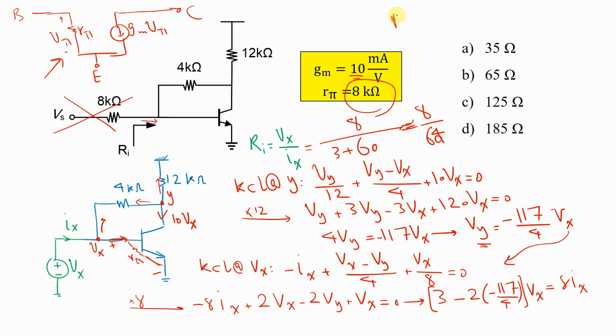So Ri equals 1 divided by 8 kilo ohm approximately. This is an approximation, and if you multiply this by 1000 to make it equal to one of these options, which is in ohm, 1000 divided by 8 equals 125 ohm. So option C is the right answer.